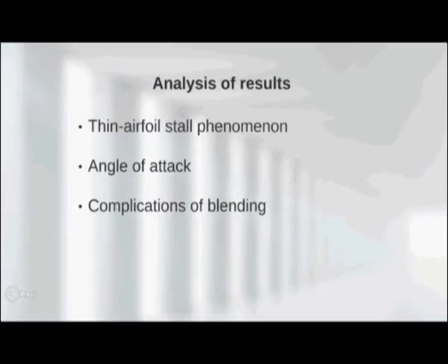We speculate that the thin SG6043 airfoil may have suffered thin airfoil stall, especially near the blade tip, where the manufacturing was proportionally less precise, thereby the leading edge was too sharp. This, along with the thin blade profile and optimization for high RPM, meant the angle of attack was too high to produce torque in low speed conditions. As a result, the self-starting speed of the turbine is quite high.